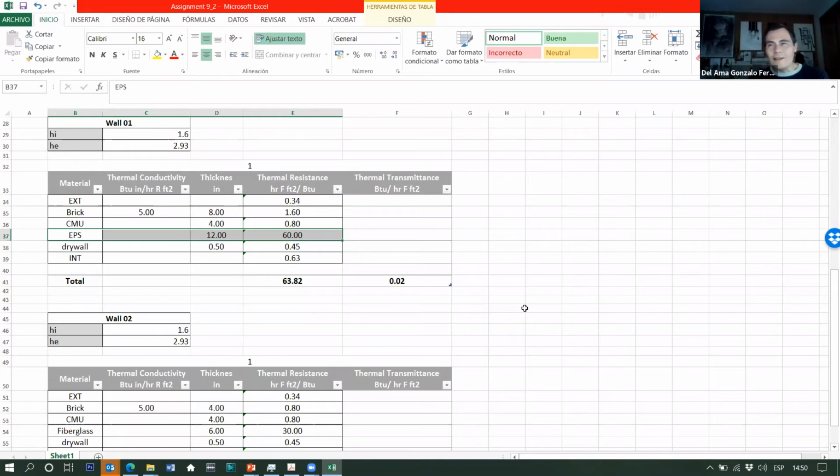We can have a table, but after 25 years of working as an architect, I don't have to calculate anything. Why? Because I have internalized dimensions. If I'm designing a wall, I know that I need at least 10 inches. 6 inches is not enough in New Hampshire. I know that. So 10 is enough, and it's very easy to remember: 10 inches, R value above 50.